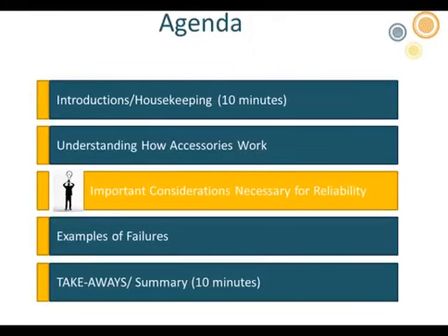But again, it depends on the manufacturer. It also depends on the type of joint or termination. Cold shrink typically will have more tolerance built in than a push-on, because with a push-on you don't have as wide a range of conductors to cover, and therefore you're not going to have as much variation in install length.